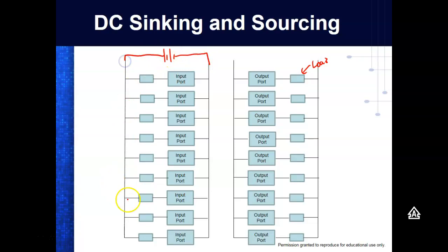And then when I connect up, you have to wire your inputs. So what that means, you have to take that positive output and run these out to all these push buttons. So that's the push button right there. Then I have to run that wire out there. The negative is internal, but I have to run the sourcing for the push buttons.